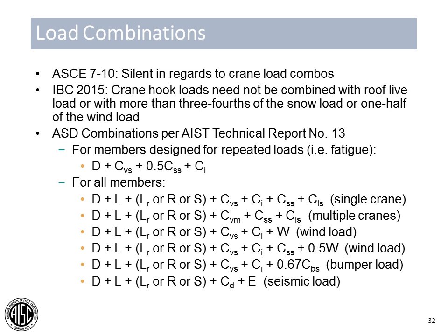This tech report does provide general minimum guidelines for both single and multiple cranes acting within a single bay, as well as what load combinations should be considered for your repeated loads or for your fatigue analysis, which we'll be discussing a little bit later. These are general guidelines and general rules of thumb, and your initial discussion with your owner should either confirm or modify these load combinations slightly.